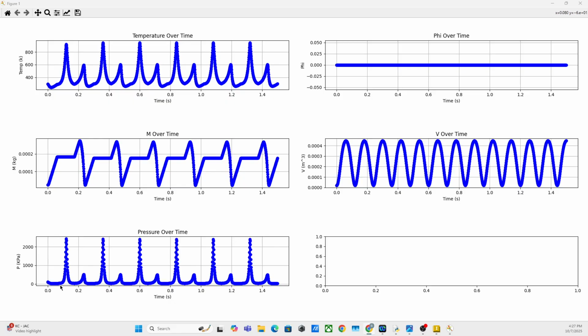And then down here is the pressure inside the cylinder. This is the cylinder compressing. This is where fuel would be injected, at the point of highest pressure and highest temperature, and then it goes back down again, and then another compression cycle, and back down again. These small spikes are because the exhaust valve isn't big enough. I'm locking the engine in, forcing it to spin at 500 RPM. As the air is trying to force its way out, the valve is restricting it a bit, so you have a buildup in pressure during the exhaust stroke. Okay, so that's just the engine free spinning. So let's add some fuel.